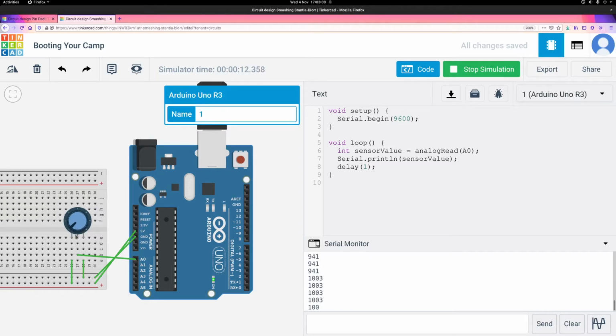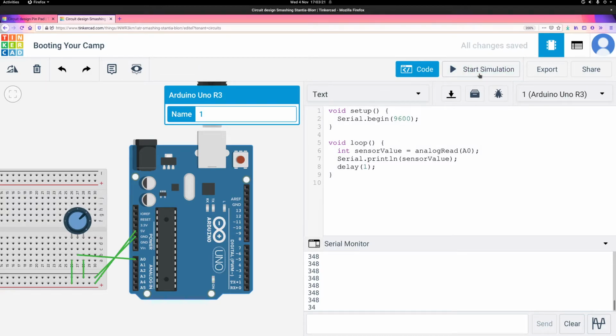Now, there's a nice thing that they built into Arduino. It's a function called map, and it works, in case you're familiar with the Python map function, very differently. What the map function in Arduino does is convert a value from one range into another.